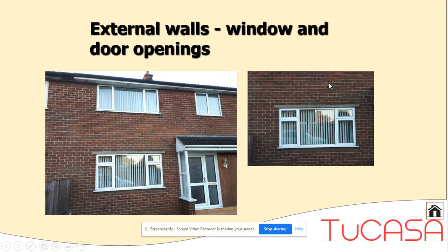So that's an indication that the reinforcing bars, probably embedded in the concrete, have rusted and corroded, and then that's not terribly healthy, because the load of the masonry above it here bears onto this lintel, which spans the opening to distribute the load to either side of the opening and safely down to foundation level.